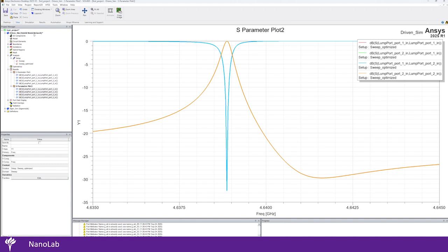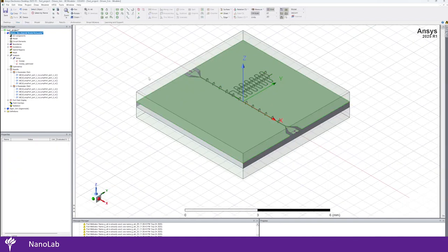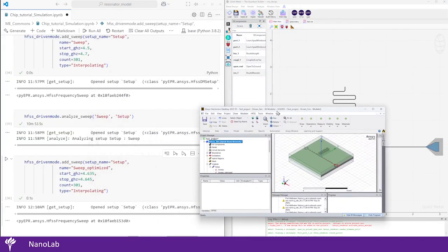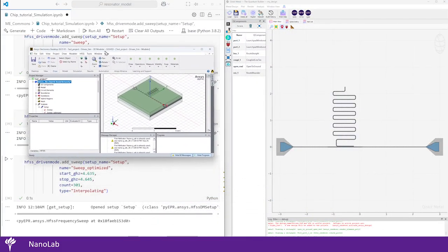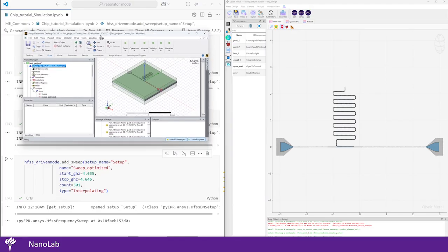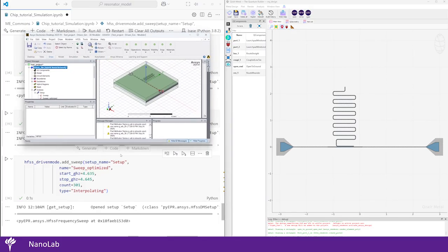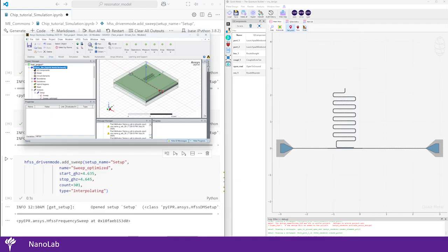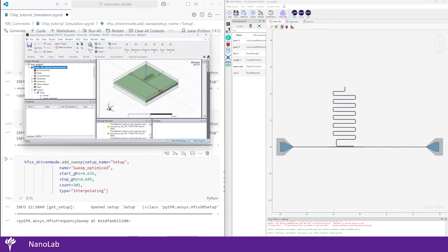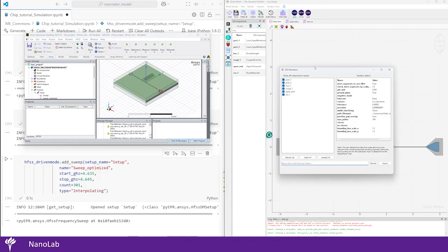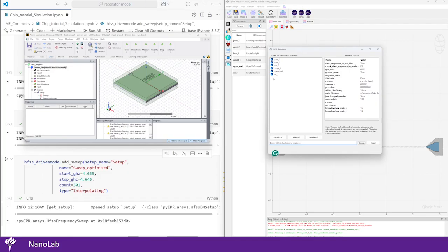After finalizing the design by doing electromagnetic simulations, we can proceed by exporting the GDS file of our design. Back to the Qiskit Metal GUI. By pressing the GDS button on top, the software will allow us to export the design GDS file by editing the file in design or dimensions, which is preferred. For just exporting the design, the basic settings will work.